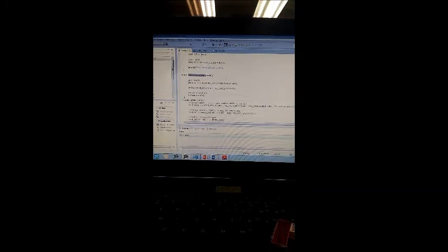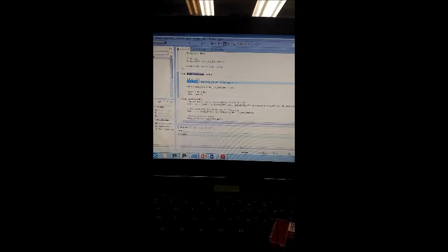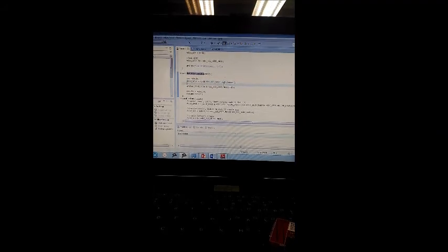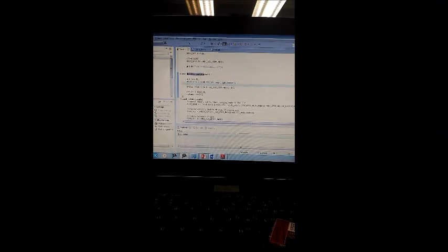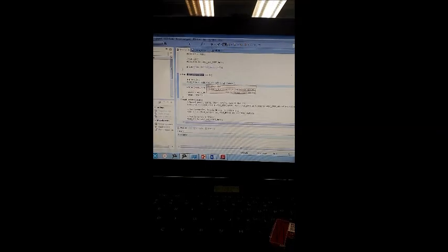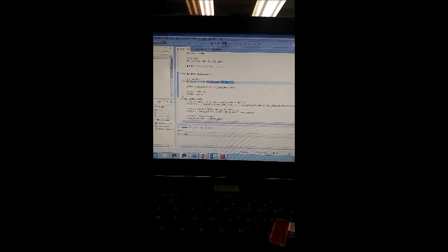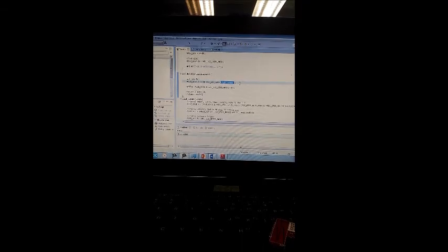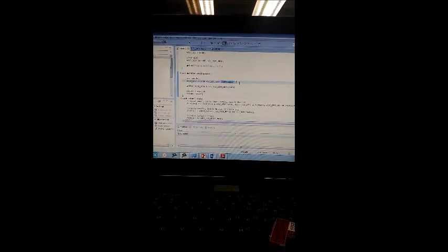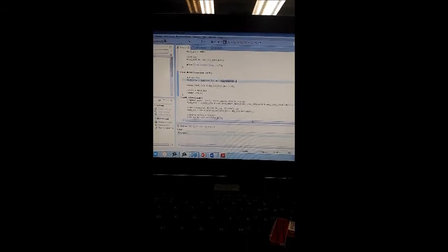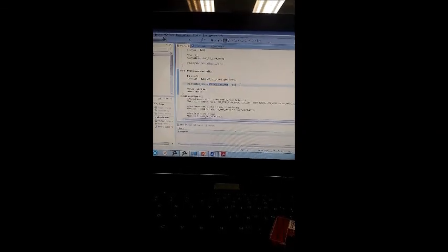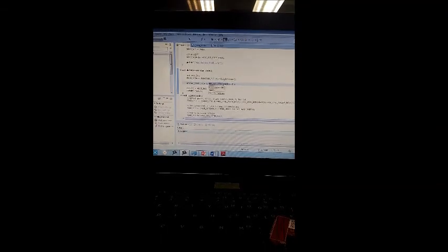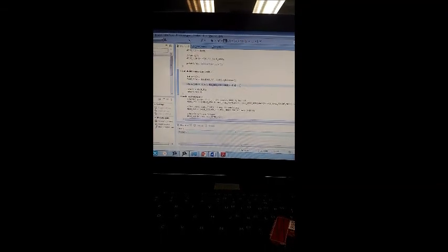So as you can see here, we first declare SC1A. So the ADC0 SC1A, we will declare it and set the ADC analog digital channel to the light sensor from just now, which is channel 19, hexadecimal 13. So while COCO mask is 0, the COCO mask is the conversion complete. So 0 means it's not complete. So while it is not complete, wait until it completes.